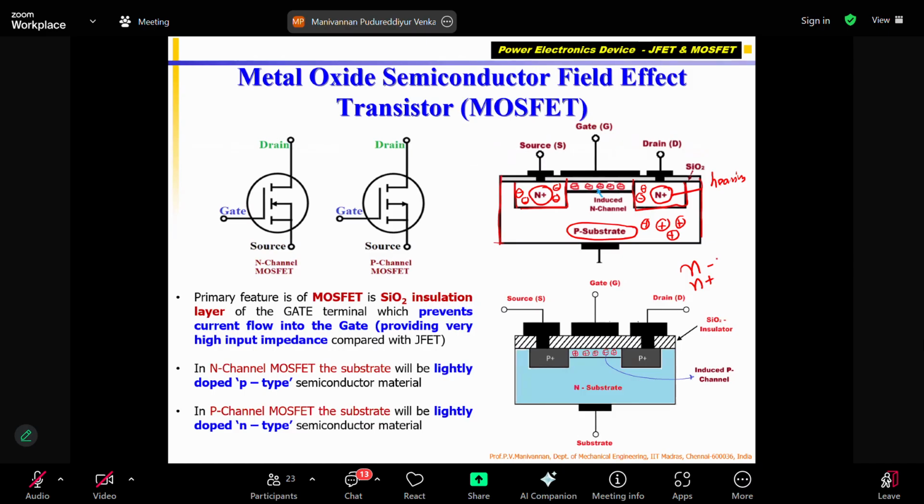So it provides charged particles, which are electrons, negatively charged. Please note that the electrons are free, not attached to any atom. So they will move inside the N material randomly. But if electrons are moving randomly, the net current is 0, because for current, electrons should move in one direction from one location to another location. If electrons are moving randomly, they cancel each other, net current is 0. Okay, that is the one thing.